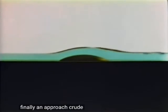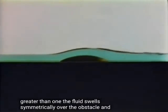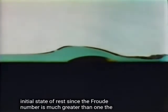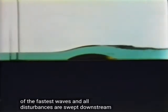Finally, an approach Froude number much greater than 1. The fluid swells symmetrically over the obstacle, and conditions are supercritical everywhere. Here's the development of this supercritical flow pattern from an initial state of rest. Since the Froude number is much greater than 1, the fluid speed everywhere exceeds the speed of the fastest waves, and all disturbances are swept downstream.